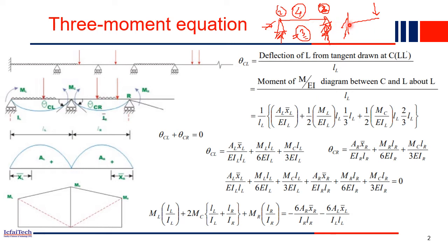Similarly, if you have a fixed-end beam, say a cantilever beam with the left-hand side fixed and the right-hand side also fixed, then you have three unknowns here and three unknowns here. So in total you have six unknowns, right? And you have three equilibrium equations. So this beam is indeterminate of order 3, because 3 unknowns we can compute using the equilibrium equations, whereas the other 3 we can't. To solve this beam, we have to draw the bending moment diagram, the shear force diagram, and calculate slopes and deflections at any point.